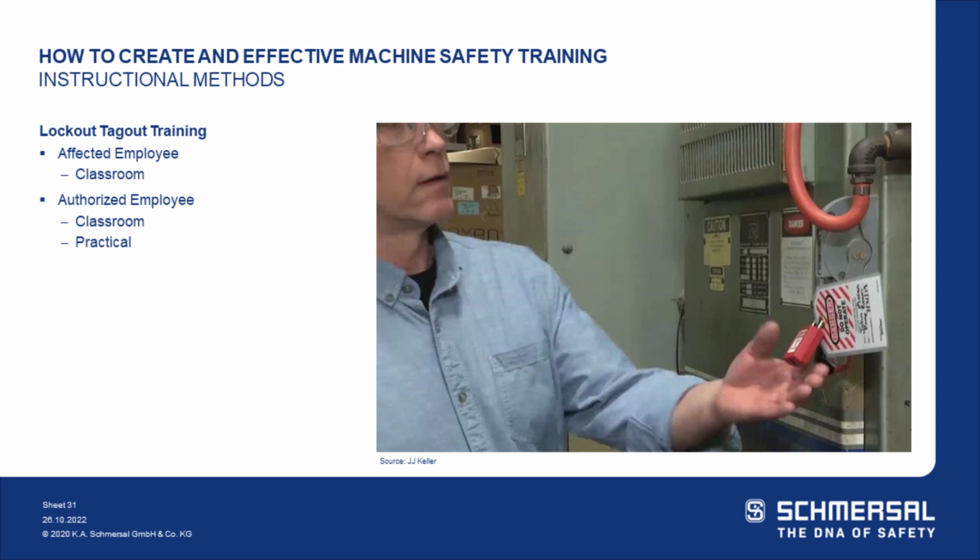For the affected employees, as you may know, you can maybe just use the classroom setting for that knowledge base, so that they are aware of what lockout tagout is, so they don't try to engage the machine when they see these locks and tags on them. Whereas the authorized employees are the ones actually performing this task. So yes, there is a classroom session where we have to have that education, but there's also a practical part where we need to see them demonstrate that they know how to perform a proper lockout tagout sequence.